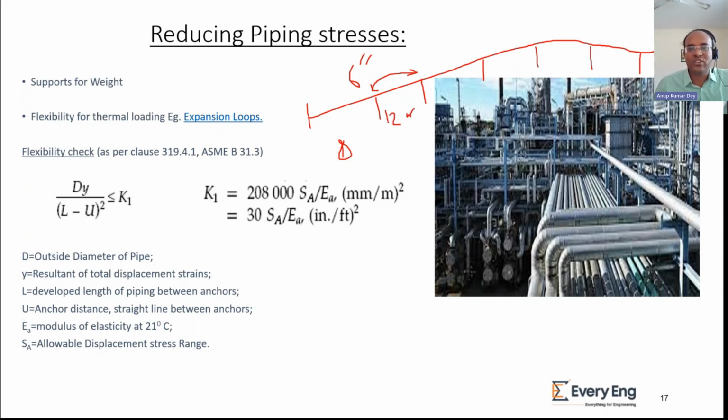then during stress analysis also, normally you will find more sagging at this location or stresses will be more at this location. Based on that, you can easily understand that your support requirement is not properly taken care of. So you can add more supports based on the availability of structure, or you can design a new structure to provide support. By adding that support, the sustained stress happening due to weight can be easily brought within allowable limit.